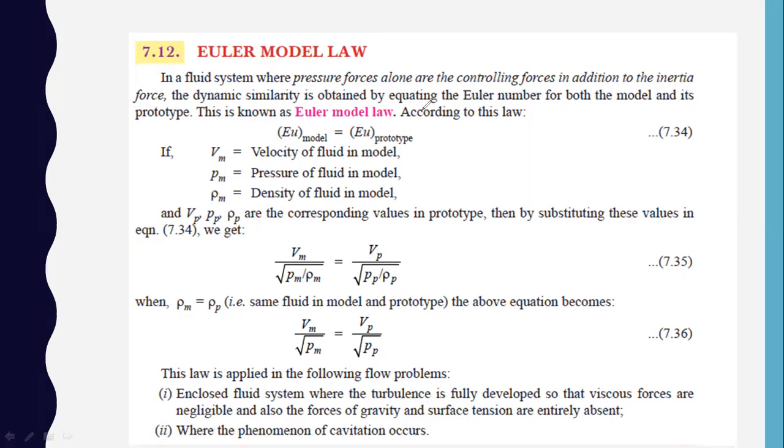So this law is applied in the following flow problems. First one, an enclosed fluid system where the turbulence is fully developed so that viscous forces are negligible, and also the forces of gravity and surface tension are entirely absent, where the phenomenon of cavitation occurs. So in these cases, we will apply the Euler model law to check for the dynamic similarity.